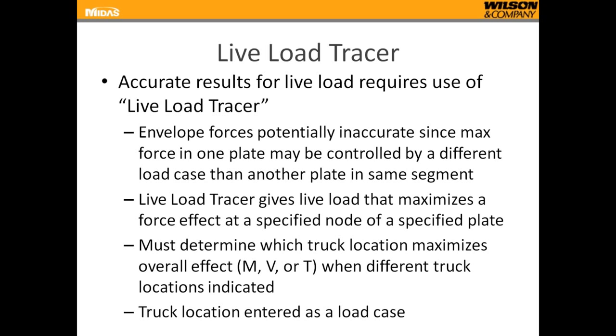It's possible that that axial load is maximized in one plate by a different truck location than another plate within that same segment. So you'd be overshooting your moments if you used envelope forces for everything. The live load tracer gives the live load that maximizes a force effect at a specified node of a specified plate.